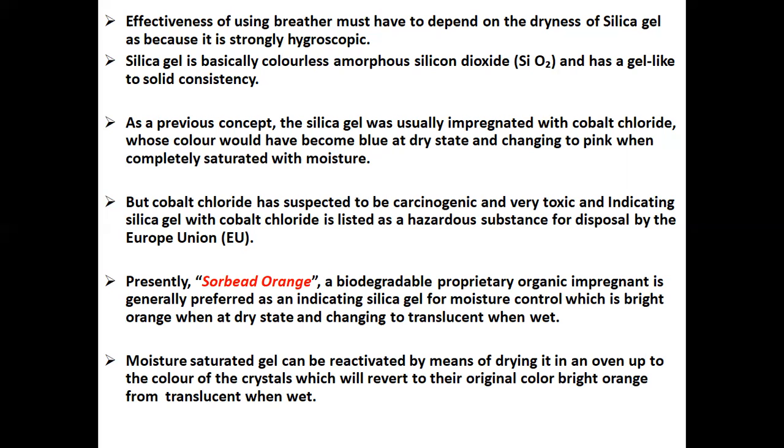Moisture-saturated gel can be reactivated by drying it in an oven until the crystals revert to their original color, bright orange, from translucent when wet.